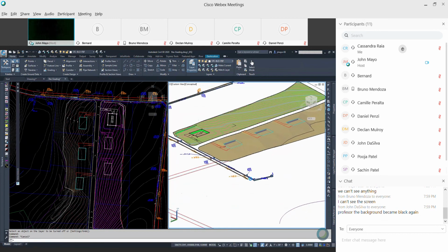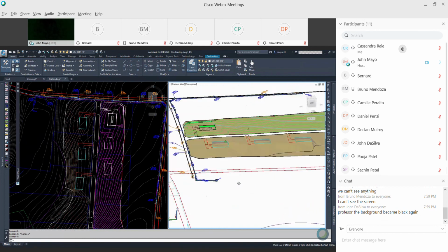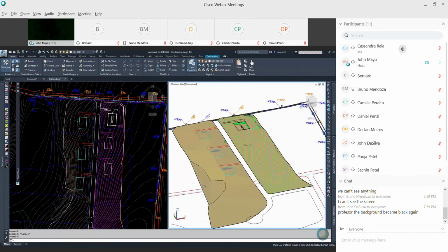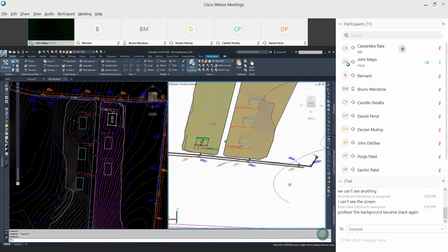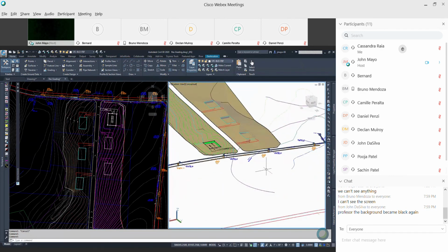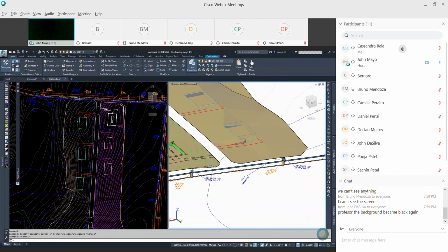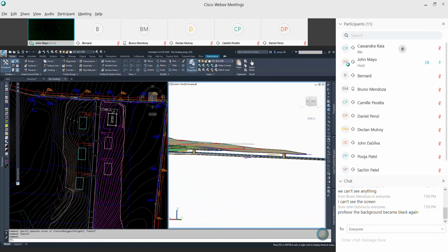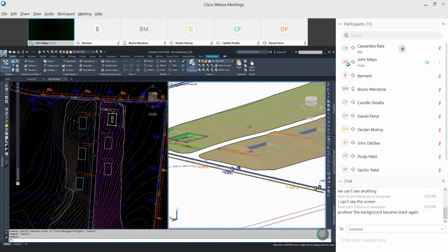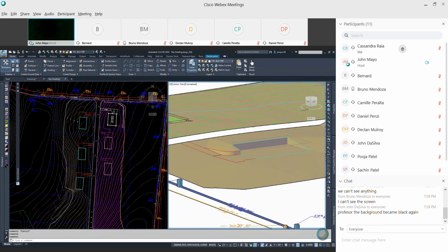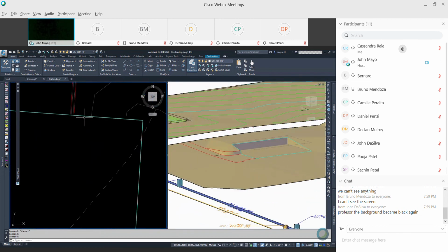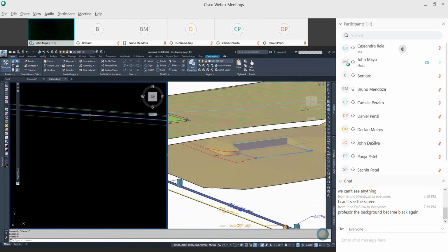We can do this again next week. But I hope you guys are seeing how all these feature line tools are giving you the same power to edit these elevations and geometry that you did when you did your roadway grading. And B, how we can make this grading scenario work.